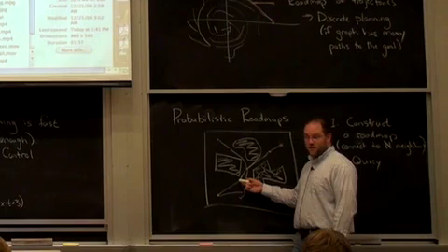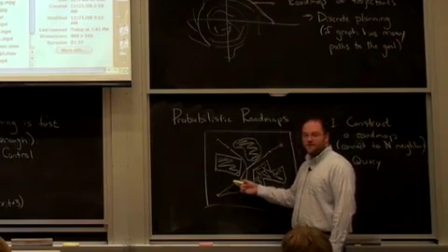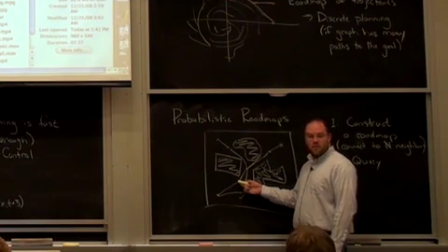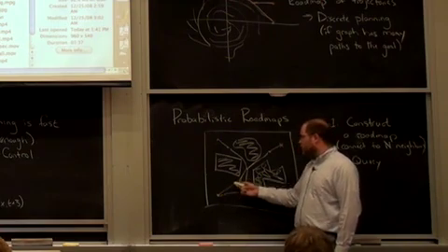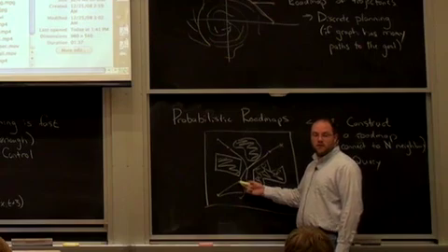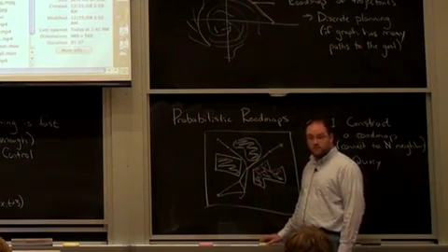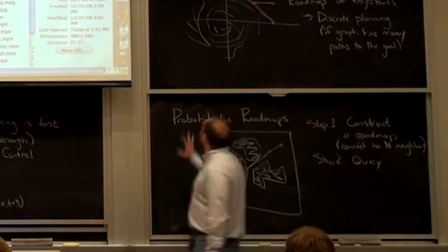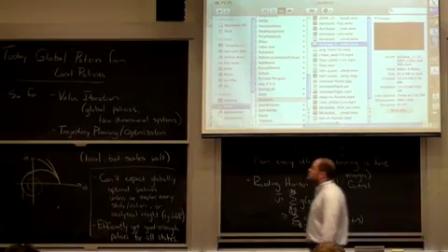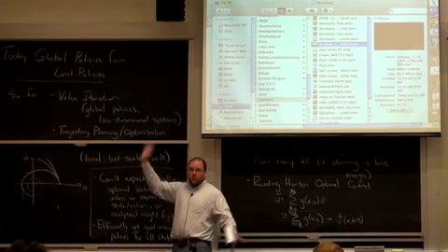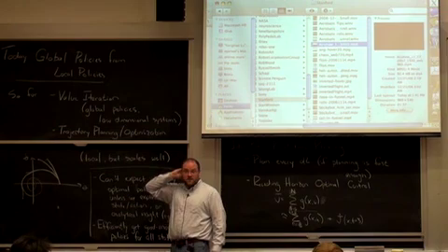And maybe to make them feasible to execute, you've got to do some trajectory stabilization. But if you can solve some local planning problems, then you can use these big roadmap ideas to maybe do more global behaviors. Okay? So again, I think multi-query planning is a nice way to go from local policies to more globally valid policies. Yeah?